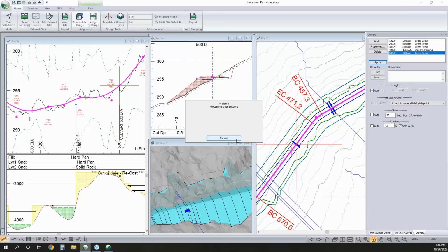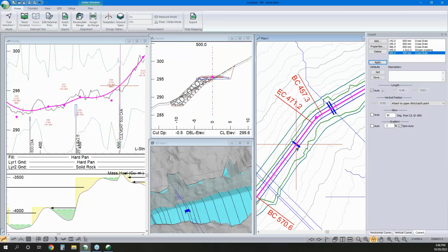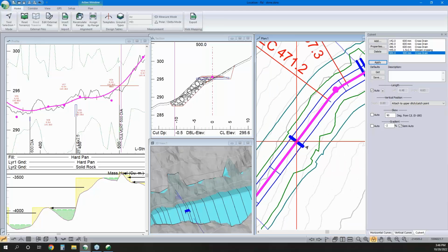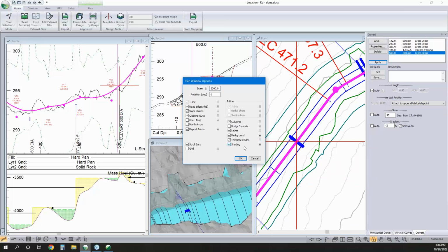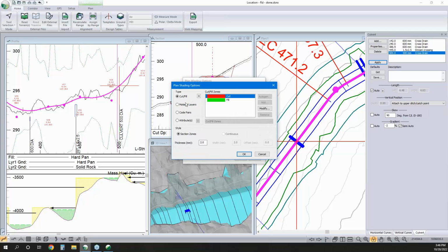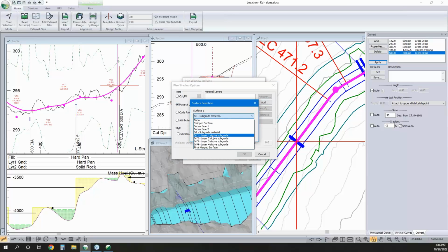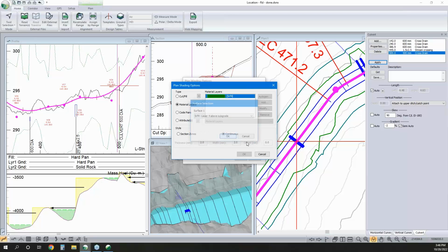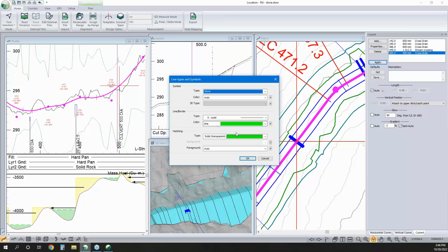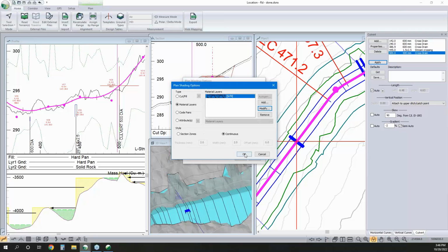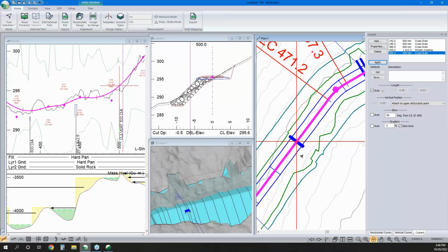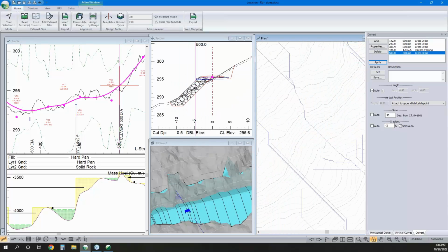And it's going through and recalculating my road. There we are. And if we want to see it here, just for the sake of it, that major culvert design that I did, I had materials layers being shaded. So here my surfacing layer 4 is what I want to show. So there we can see that armoring being applied.